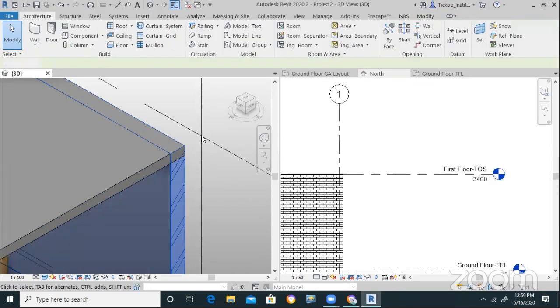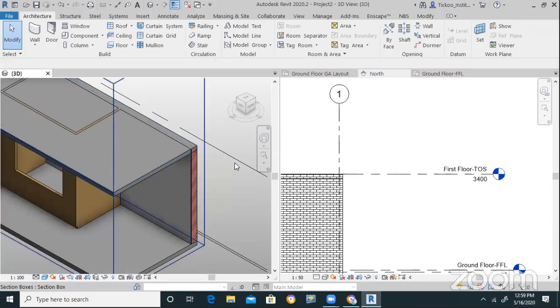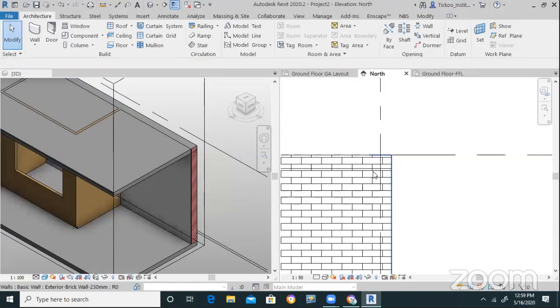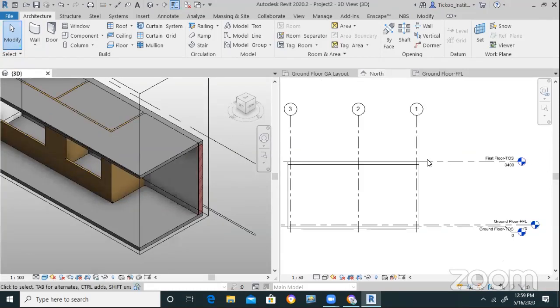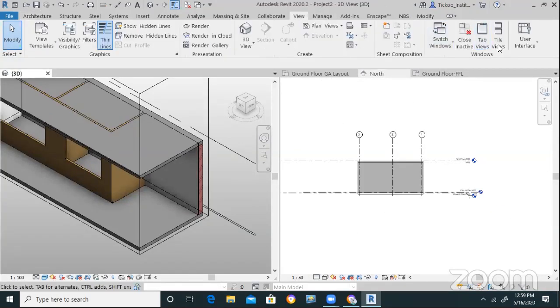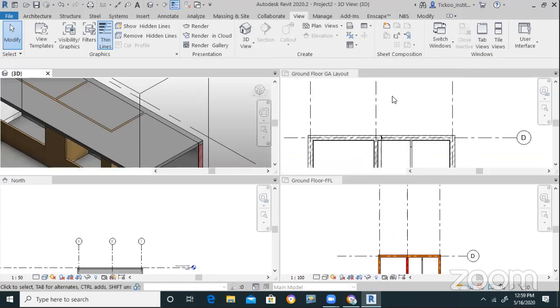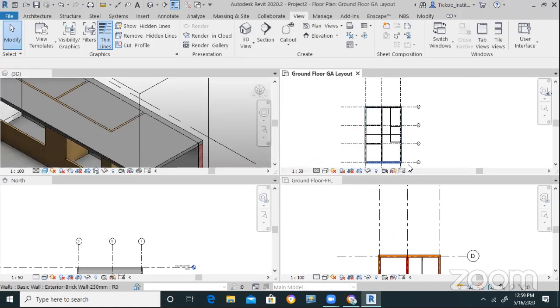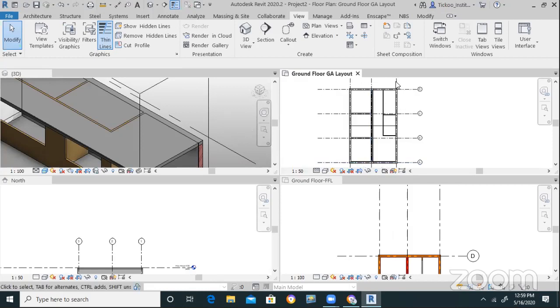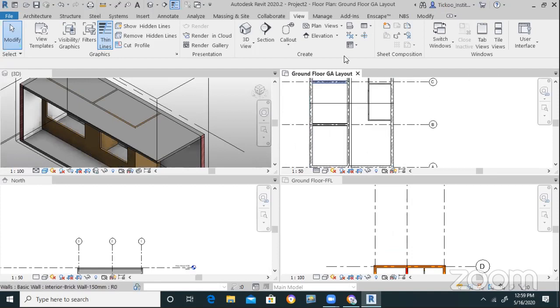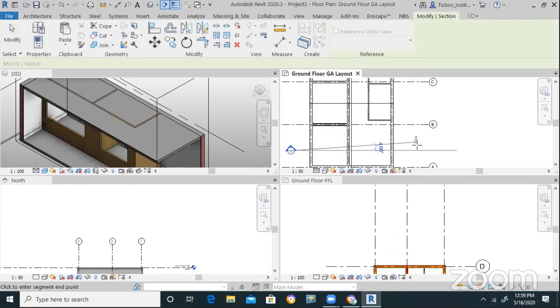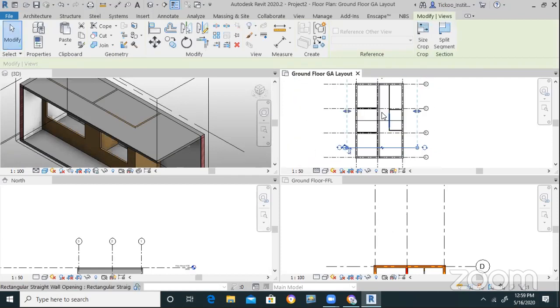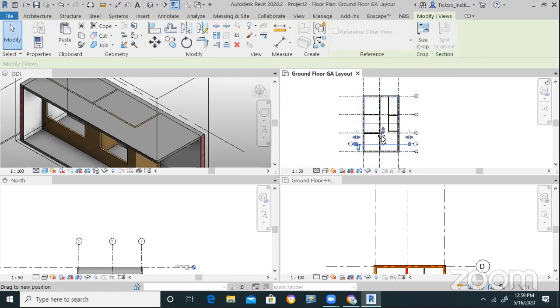Now you can see that the height of the wall is basically finishing crossing here. So there are certain tools that you can do because they are on the same level. So if you can see that the wall and the height are overlapping, the wall and the slab. So let me do one thing over here. Let me tile it, draft a section. So I'll draft a section at, let's say, here, in order to see the intersection of the walls and the slabs.